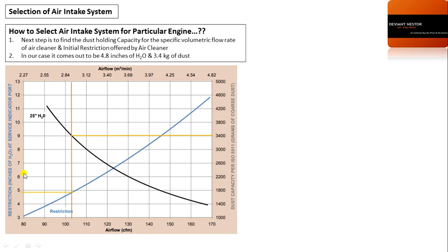and we know that pressure drop or pressure is equal to h rho g, p equal to h rho g. H is the height, in this situation h inches of water, that is 4 inch, 5 inch, 7 inch, that we can convert in meter, mm, whatever is suitable to you. So we will get restriction and airflow. As we can see from this graph, as we increase the airflow, restriction also increases. Although this is not a linear graph, somehow it is parabolic.